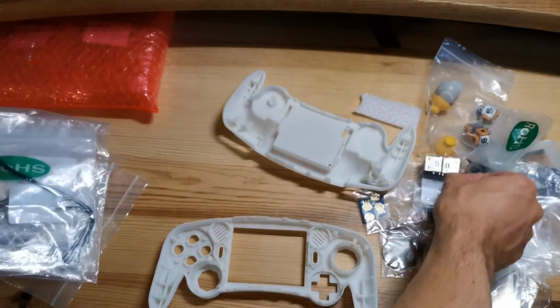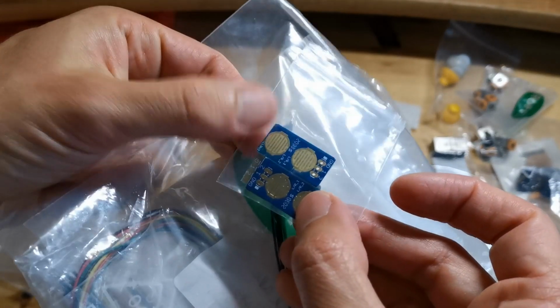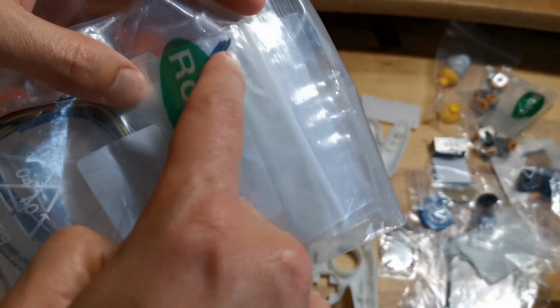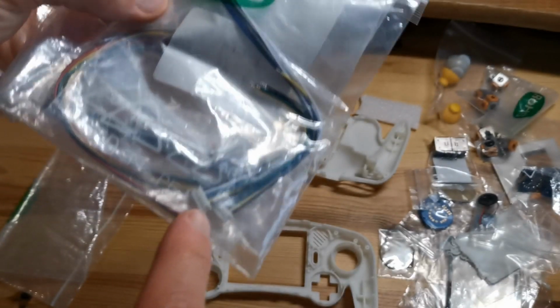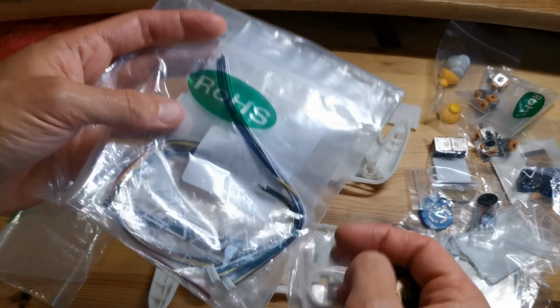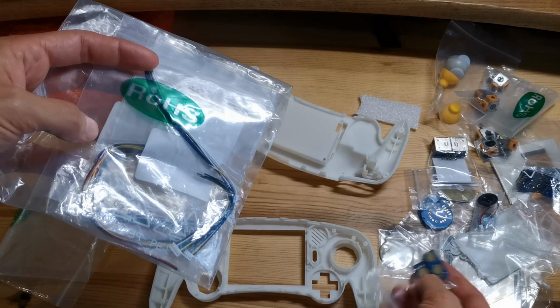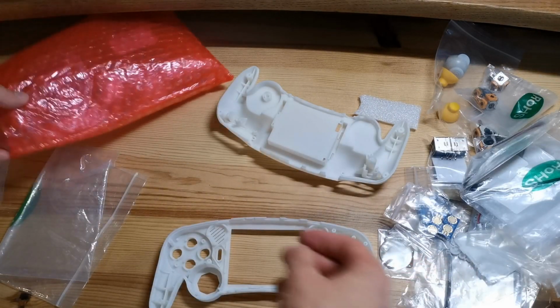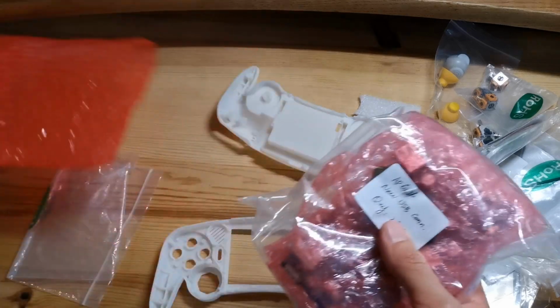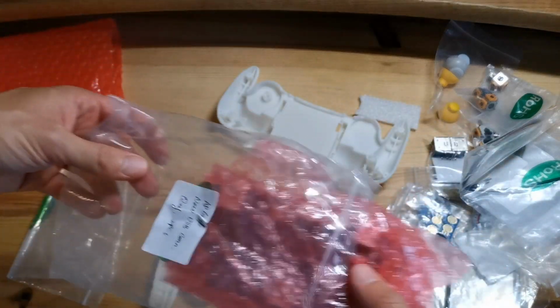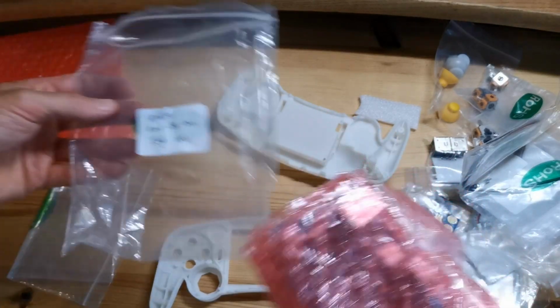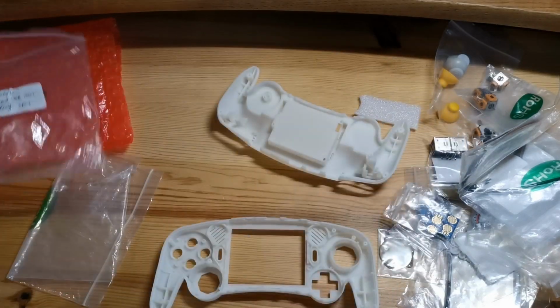Because each of those small PCBs that I showed you before has small vias here, each one of these PCBs will be soldered to one cable, and the cable will connect to the main board with those connectors. So we will have to solder all of those cables to the small PCBs and check if everything is okay. And now the main part of the prototype is the PCB. So we have two different packs of PCBs, because we will try two different Wi-Fi modules actually, but otherwise it's the same PCB.